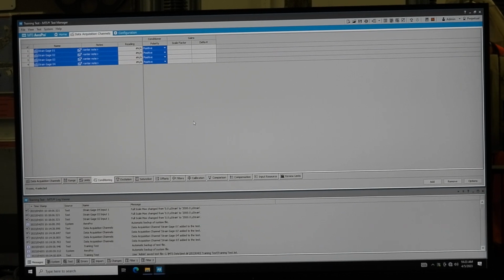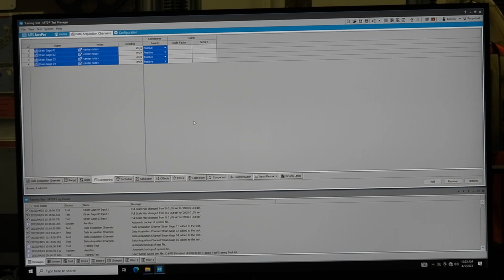Yeah. Well, the nonlinearity is documented: at 1,000 microstrain, you're 0.1% off. At 10,000, you're 1% off. Or I might be off by a factor of 10, but it's 0.1% to 1% to 10% fairly quickly. Might be 10% at 10,000 microstrain. That's what it is. And this calculation is meant to, or does, compensate for that known nonlinearity. So I don't know that there'd be benefit to not use it, is what I'm thinking. Unless you wanted to record it as nonlinear and post-process it yourself later.